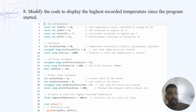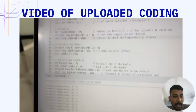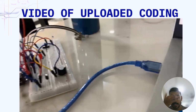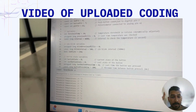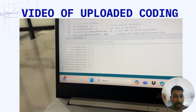So next is to modify the code to display the highest recorded temperature since the program has started. So this is the coding, and this is the video of the uploaded coding, and as you can see, the serial monitor is recording 37 degrees Celsius, which means that is the maximum temperature that it has sensed since the start of the program.